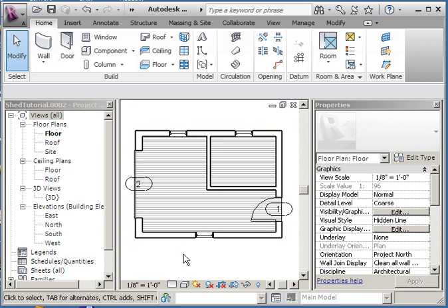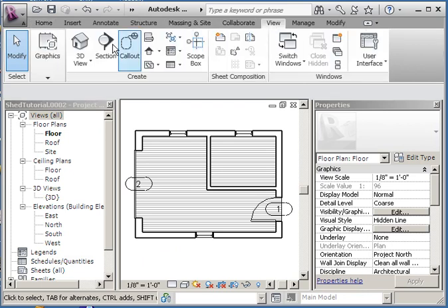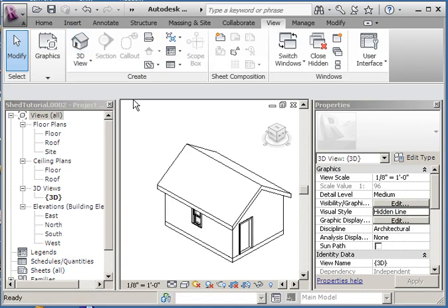So now we move on to step 12, and we're going to be looking at 3D view. So it says open a 3D view. You want to click on view and 3D view, and there's my house. And we're trying to get a rendering done, and so create a realistic shaded view and select the visual style icon in the view control bar at the bottom of the interface. So that's right along in here.